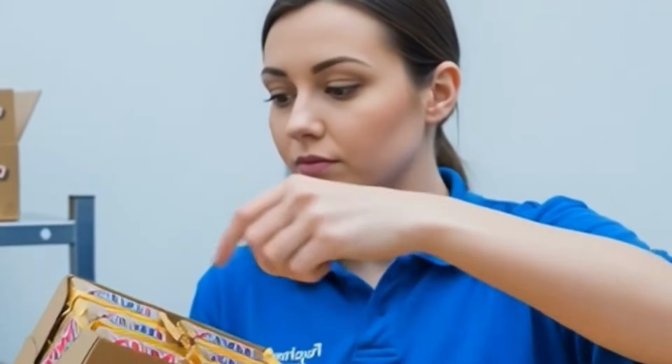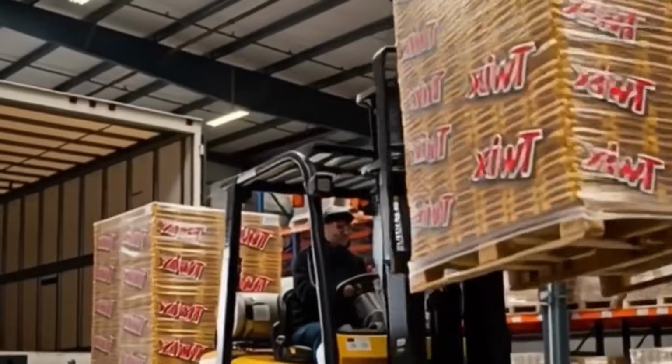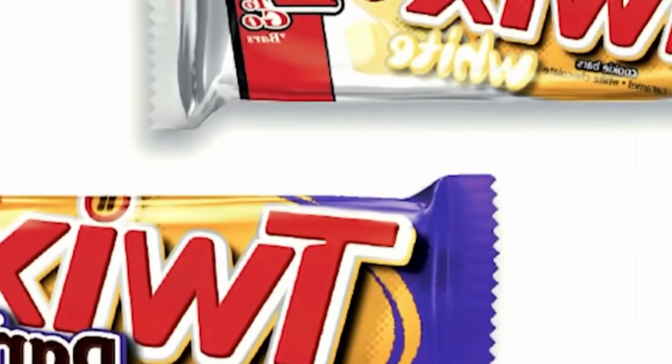After baking, the biscuits are transferred to a mesh cooling conveyor where ambient air is forced from both above and below using axial fans. Surface temperature is reduced to under 30 degrees before the biscuits are sent downstream. During this phase, any misshaped or cracked bases are automatically rejected using laser sensors and high-speed diverters.